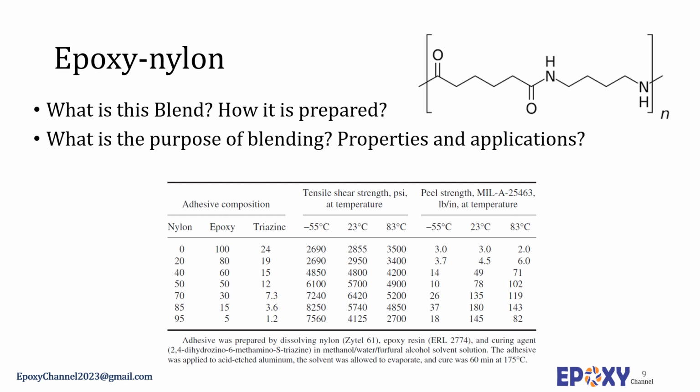Epoxy nylon adhesives offer both high tensile shear and peel strengths. Epoxy nylon adhesives can provide tensile strength greater than 5000 psi and peel strength greater than 15 pounds per inch. In addition, epoxy nylon adhesives have good fatigue and impact resistance. They maintain their tensile lap shear properties at cryogenic temperatures, but the peel strength is poor at low temperatures.